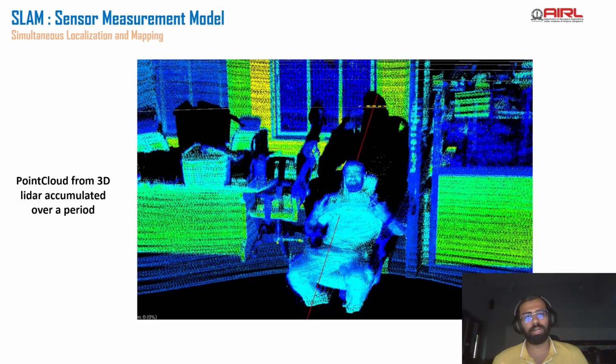That's because other than just range and bearing, it also gives me the intensity. Different materials absorb light in different ways, and that intensity is also captured when the reflection comes back to the sensor. Something like a number plate would be highly reflective, versus something like charcoal or a black road, which would have a lower reflection compared to other things.